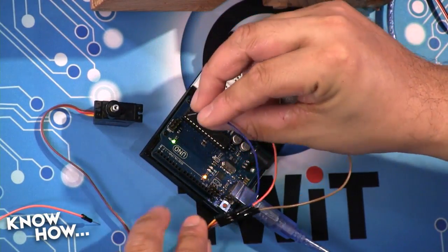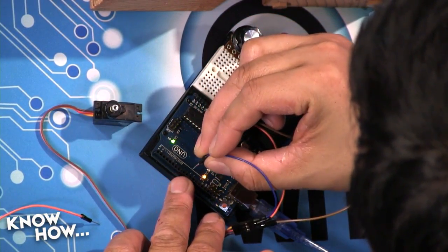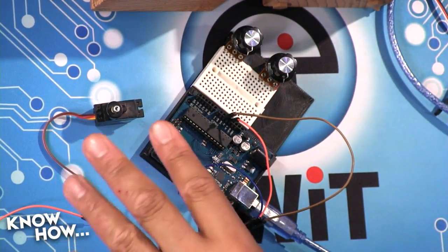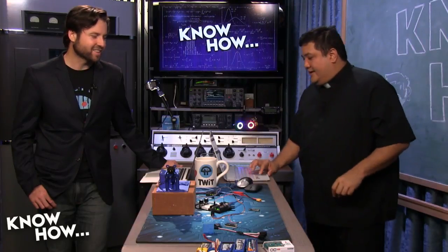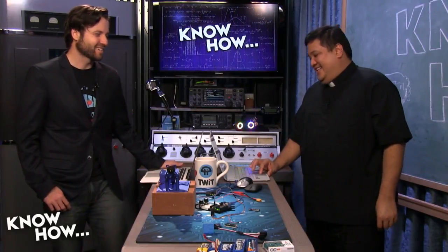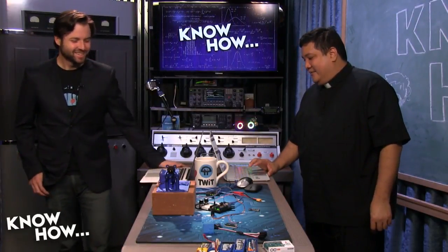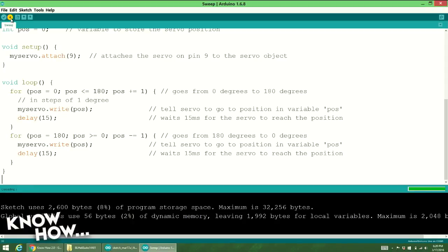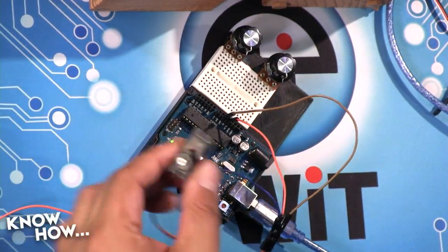So I'm going to take this and connect it to 9, which is the pin that I want. And you've heard it already. I thought that was the noise of the pin going into this. Okay, so I'm going to upload. Go back to my screen, Alex. This is going to compile the sketch. Then it's going to push it up through the COM port. And once it's done, there we go. I can hear it.